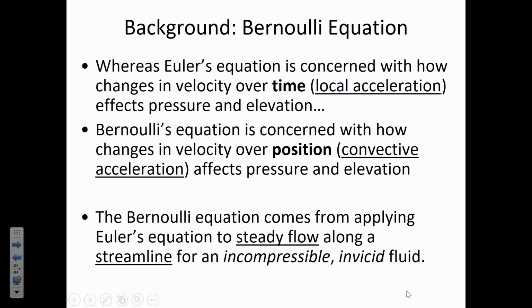The reason why that's important is that Bernoulli's equation is saying that there's some change in pressure that occurs when the velocity is adjusting. And if your fluid is changing in density, then there would be kind of a third degree of freedom there on why the pressure is changing. So just to take that uncertainty out of the mix, if you're dealing with an incompressible fluid, you're saying that as a fluid goes through a nozzle, for example, its density remains constant. That's why we have the incompressible assumption with Bernoulli's equation: we assume that between 2 points the density of the fluid stays the same.